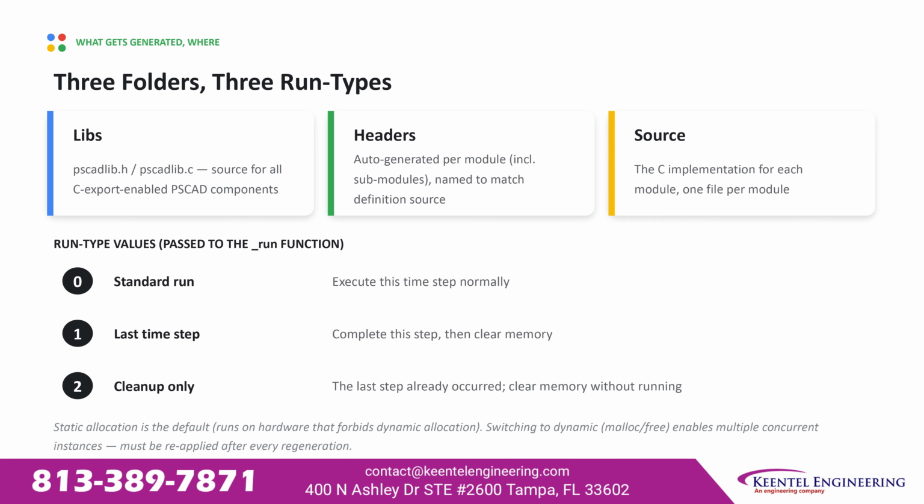Memory allocation defaults to static, which is required for hardware targets that forbid dynamic allocation. Switching to dynamic allocation enables multiple concurrent instances but must be reapplied after every regeneration.